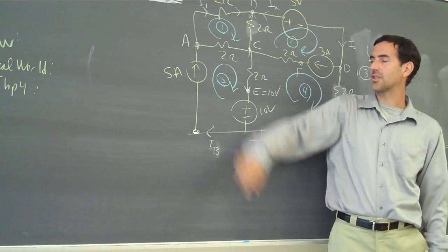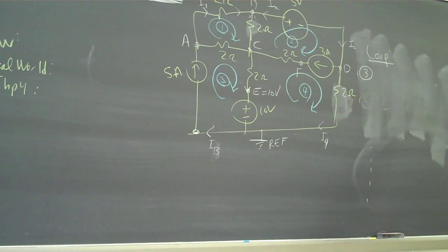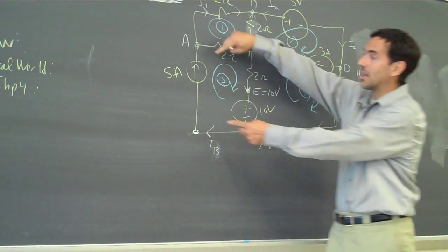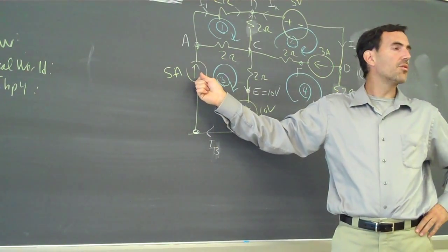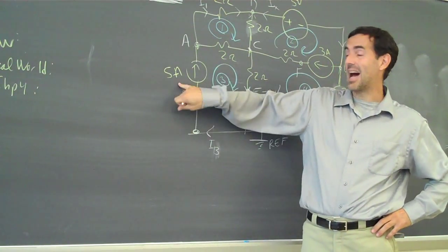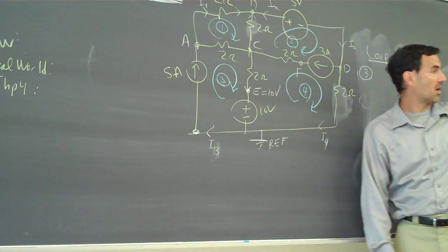The voltage across a current source, we don't know. And this is when a lot of you were asking me homework questions. Oh, I've got this mostly done, I got stuck on the loop analysis. On the loop analysis, if you got stuck, it was likely you were getting stuck when you saw a current source. The voltage dropped across a current source is not 5. This is 5 amps. It tells us nothing about the voltage drop across it.